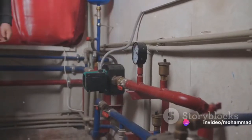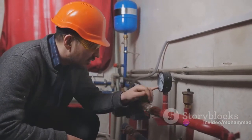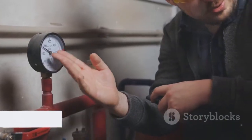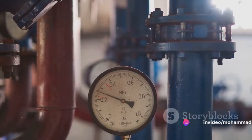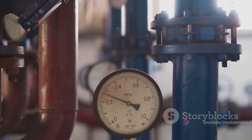So, to measure flow rate, we need a DP transmitter and an obstruction such as an orifice plate. But there's more to this process. Stay tuned to find out more. Now, here's where it gets a little tricky. The differential pressure is proportional to the square of the flow rate. That doesn't give us a straightforward measurement, does it?